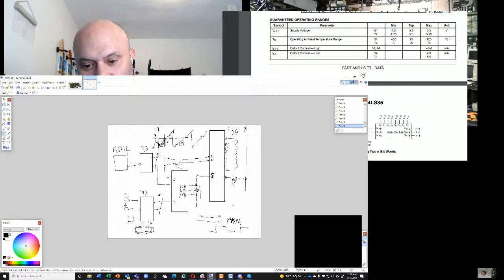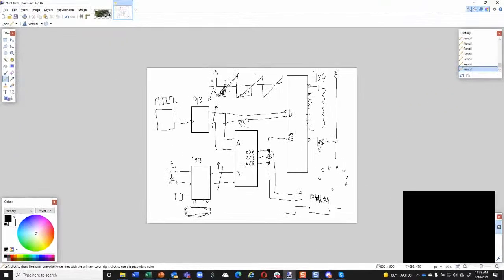And so you arrange your LEDs in a circle of 16 of them. And because this is counting very quickly at several kilohertz, maybe 20 kilohertz, you don't see any flickering. It looks like they're all just lit up to the set point, and then they're off past the set point. And so this was my little model